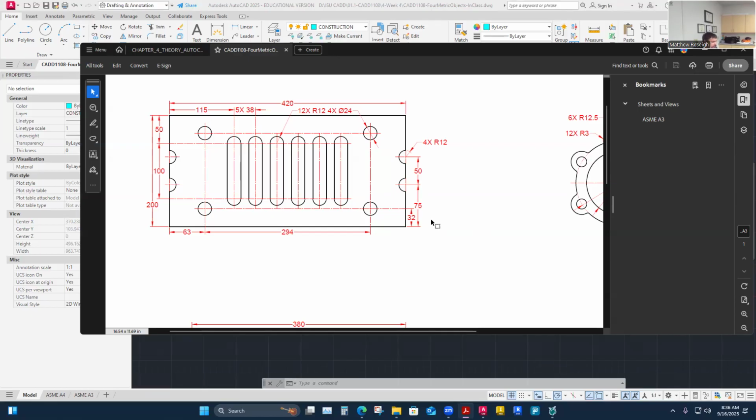So I would approach this part with the whole pattern being a critical dimension. That's why I like the 294 hole to hole spacing, and I feel this hole to hole spacing should be added to the dimensions as a critical hole dimension.